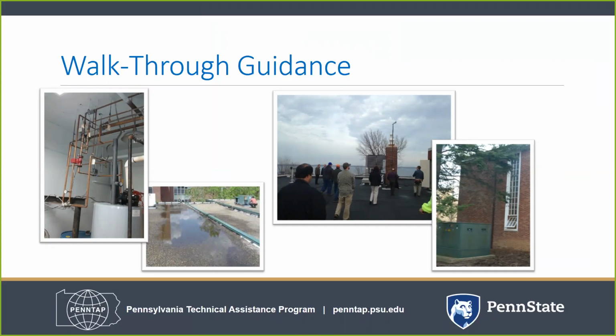When you are investigating or doing your walkthroughs, look at the building's conditions and operations. Use your senses. You want to look, listen, smell, and touch. Obviously, when you're touching, make sure that you're not touching anything hot. But smell, when you're going by motors, do they smell hot? Or do you smell rubber burning, belts and things like that? Listen, does it sound right? Do you hear things that sound maybe loose? So you really do want to use your 5 senses when you're going around.